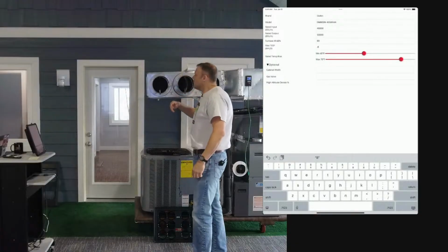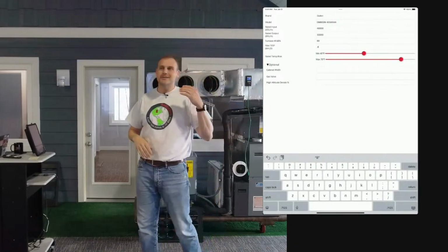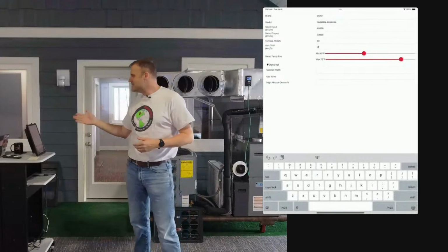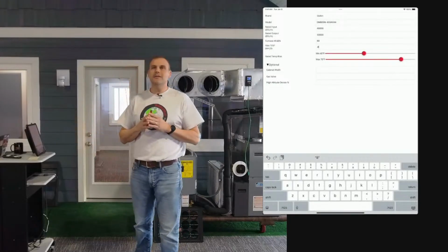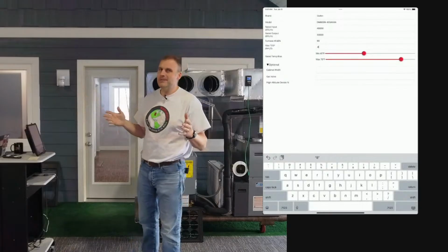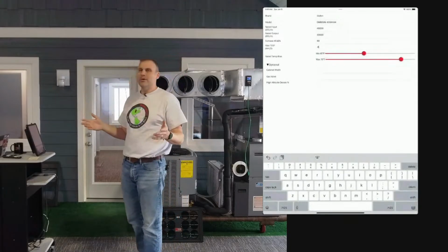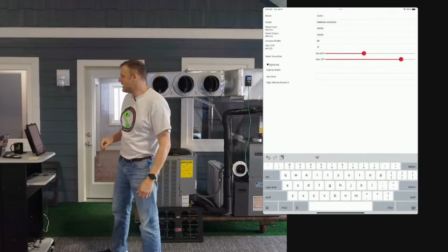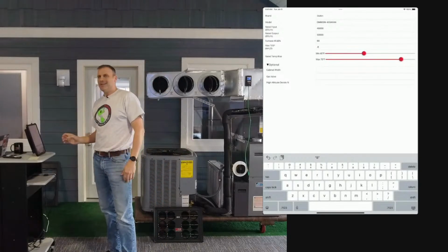Okay, so what is the difference? There is rated static and there's the blower curve chart. And when you hear max TESP, you want the limit of the blower curve chart. Sometimes that's hard to find. 0.8 is the default. Why? It's the most common. That's why. Okay, conquered that. Let's keep going.